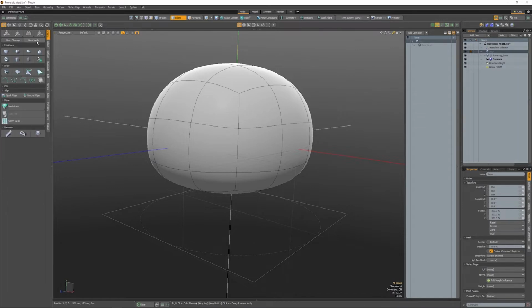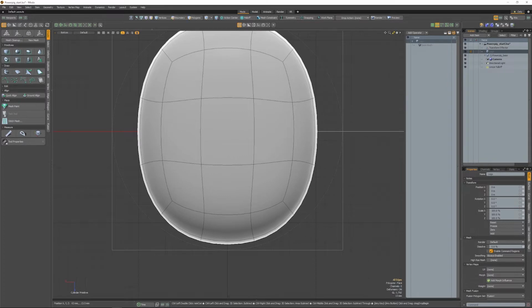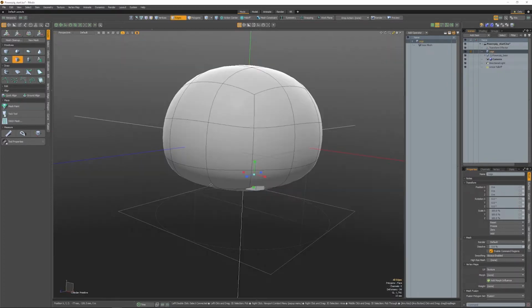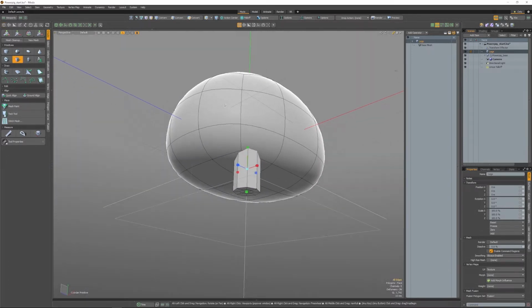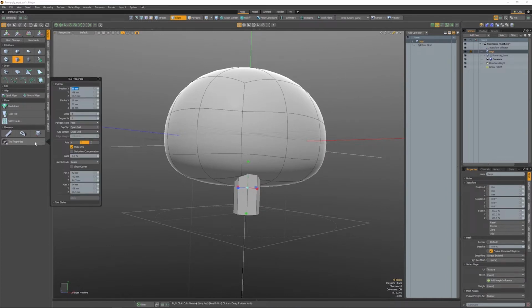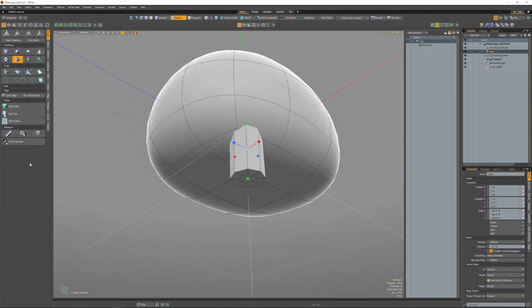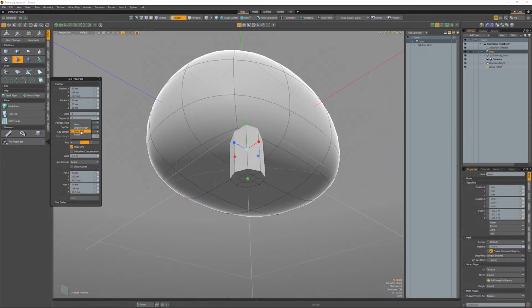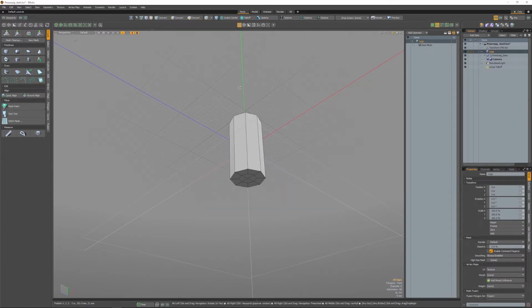And let's come here with a cylinder tool, bottom view, press Ctrl and drag to the size you want. In perspective, pull down, make it bigger to enter the volume a little bit more. And here you should also always try to aim for quads. Meshfusion prefers quads, although it can also handle triangles and n-gons, but especially on the areas of intersection, you should have quads. Right, so this one is alright. So I can isolate this one.